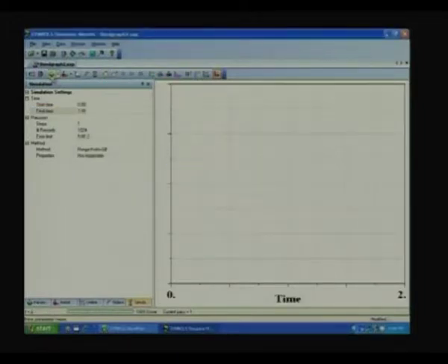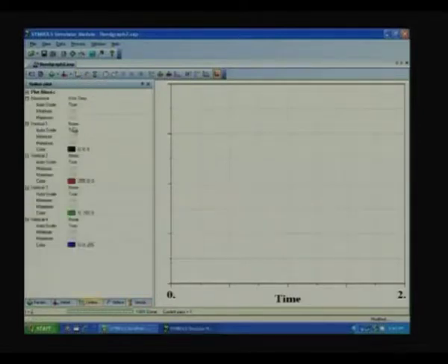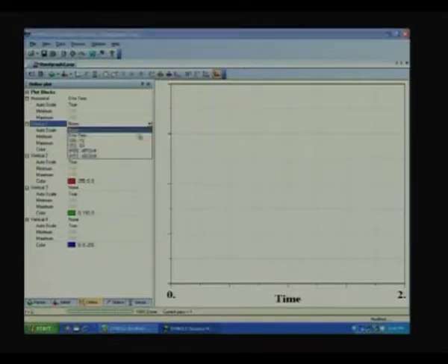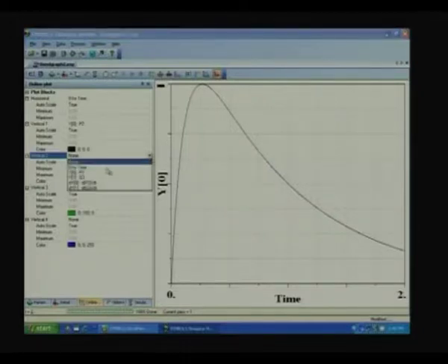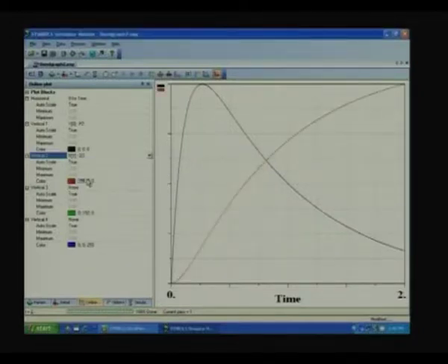We have not given the plot blocks. So, 0, the horizontal is time, vertical 1 I will give P2, and vertical 2 I will give Q3. Okay. So, that is what you expected. Notice that Q3 is the voltage across the capacitor, it starts with 0 slope, that is what we predicted. It goes up and tries to reach the final value V. The current goes up and down like this, that is what we predicted. So, what we predicted logically were actually correct.